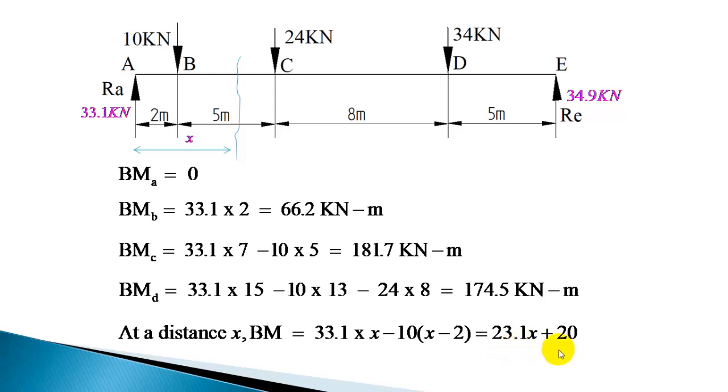We already showed in the previous class that the bending moment variation due to point loads is linear, or a straight line equation you are getting for that. So it's a straight line equation, and bending moment variation is linear variation. So you can always plot the bending moments by straight lines when point loads are acting.